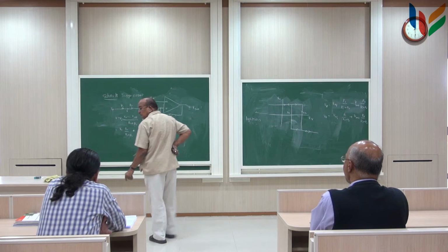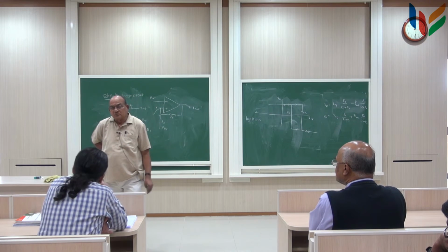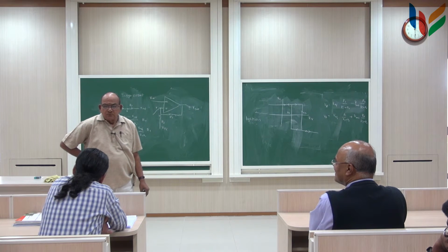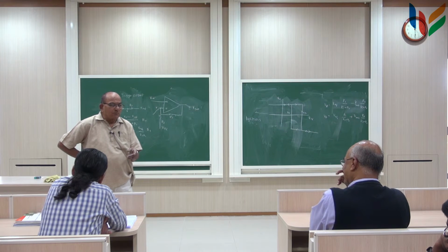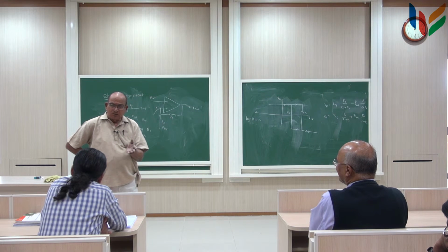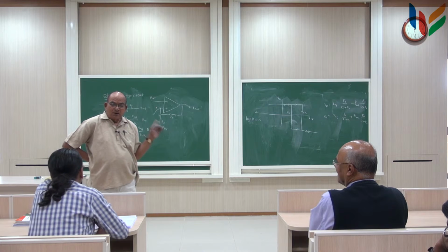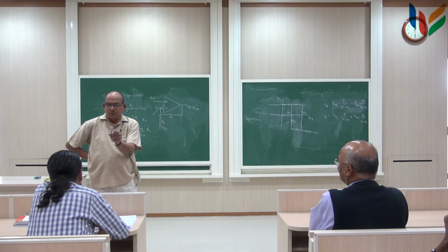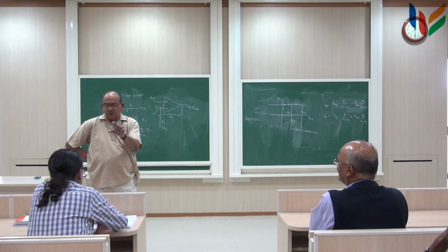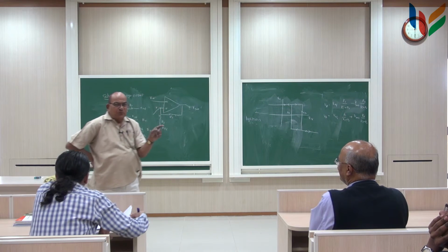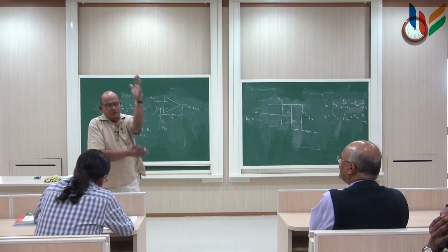And sir, this is the second time in this course you have put the feedback on that positive terminal, sir. So that's not a God-given rule that we can't do it. Normally, for stability purposes, you do not want an output to be connected to the positive terminal of the input. But here I am intentionally doing it because I want to make the window of this operational amplifier input voltage as small as possible. So, this positive feedback is actually making the curve vertical.